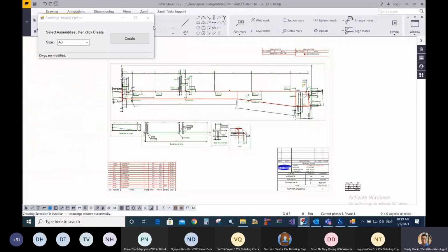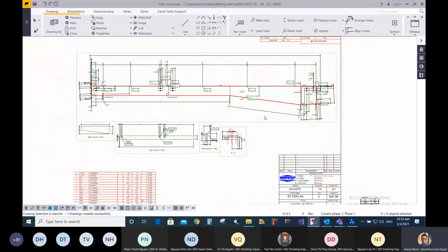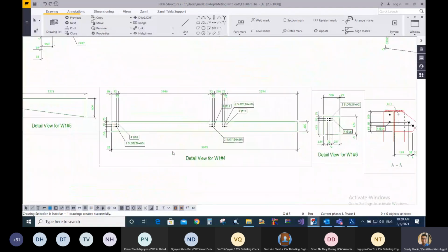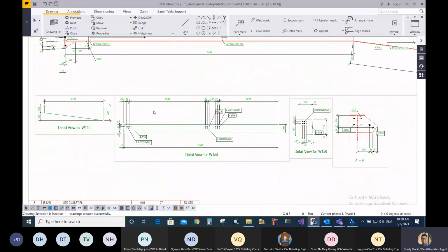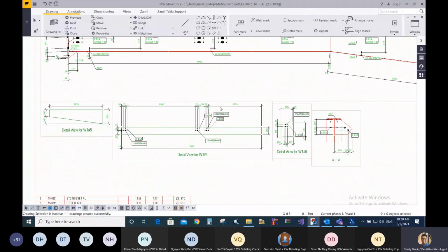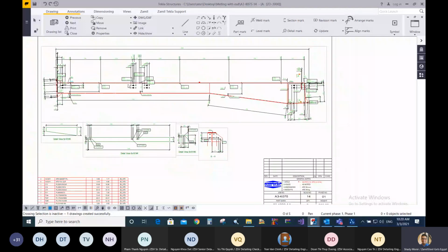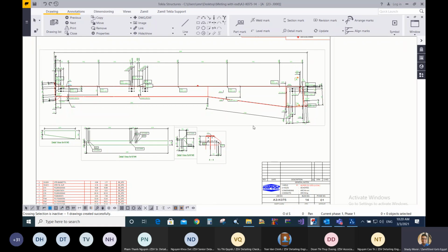Okay. So this is the rafter, okay, and this is also the web details. The web cutting diagram is created. Maybe in some conditions, if you have a lot of dimensions and a lot of members to be fixed, you will feel that it's better for you to increase the scale. Maybe you can, for example, just go for the view